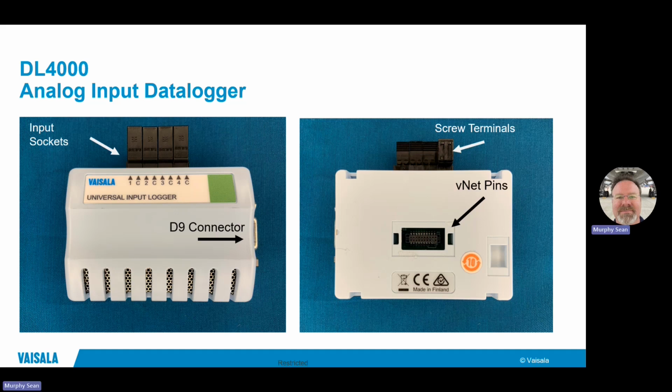The DL4000 data loggers, like all the other data loggers in the DL series, primarily communicate using RS232 serial. Serial port servers are required to be able to convert the serial communications over the network. So there's always another device, typically with a viewLinc integration.